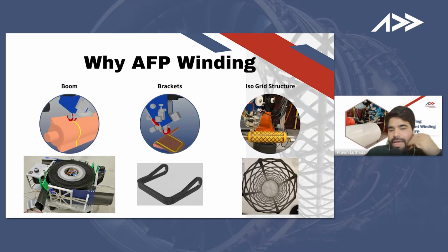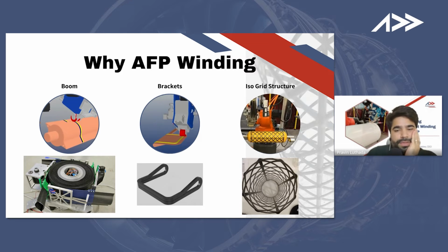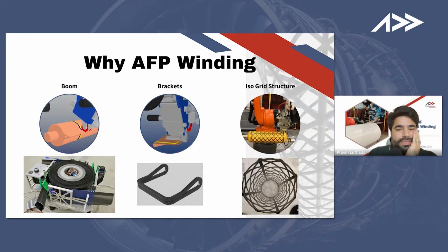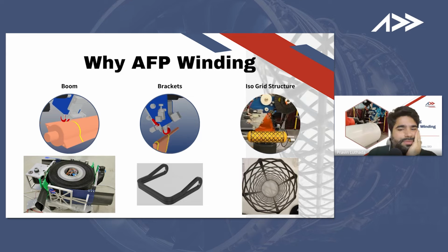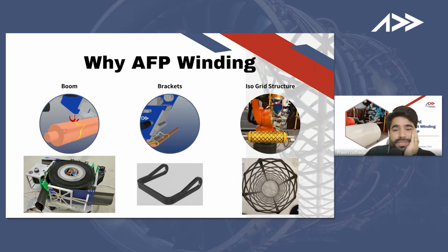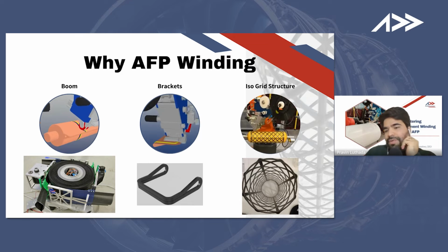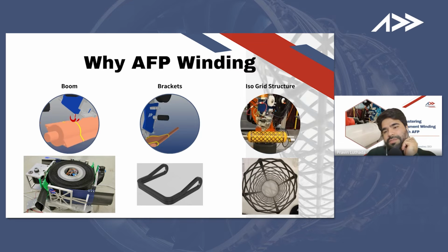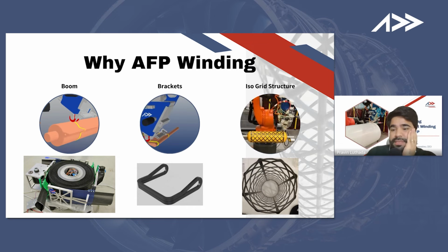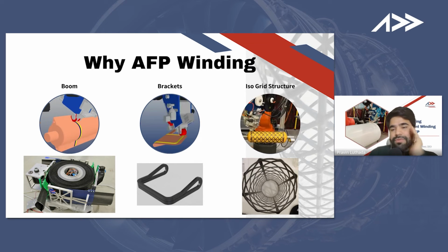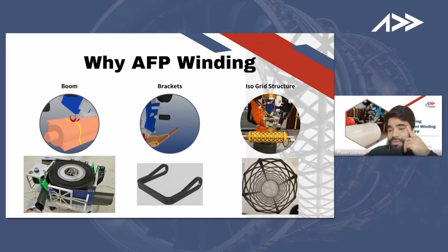Here is one of the applications, which is a load bearing bracket, where you're doing the fiber steering. Once again, this is more of a hypothetical example because fiber steering at that level may be a bit too optimistic. But the bracket design with the grooves is actually possible. This is, I think, one of the very famous structures, isogrid structures, used in the space industry quite a lot for upper stages, but making entry into automotive also. And this, at the moment, filament winding is not capable of doing because of the manner in which the grid is made.